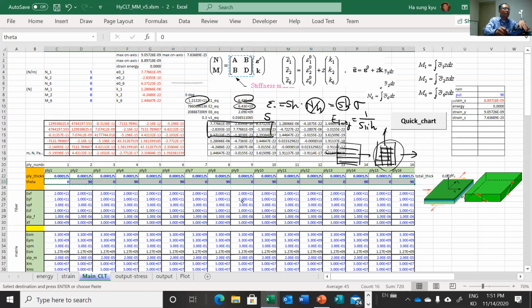This is only 61 versus 121, right? It's obvious because in each direction we have only half of the number of plies, and the same for the other direction. So as you can see, stiffness is almost half.